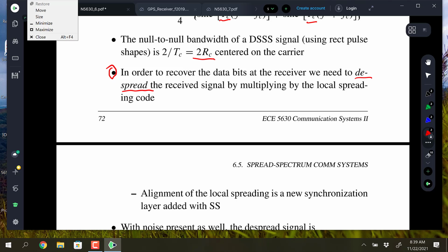Everybody got a very long spreading code, and through your SIM card, the SIM card that's in your phone, that was unique to you. Maybe the number of codes that they could give out through the SIM card is finite, but it's spread around the world so that no one would have the same spreading code. And what you get is not really a spreading code. This code is really long. Just think of it stretching from way over there to here. What you got with your SIM card is a starting position. Does that make sense? That was your identity with your SIM card, where you are in that spreading code. It's the same sequence, but I'm going to start from here.